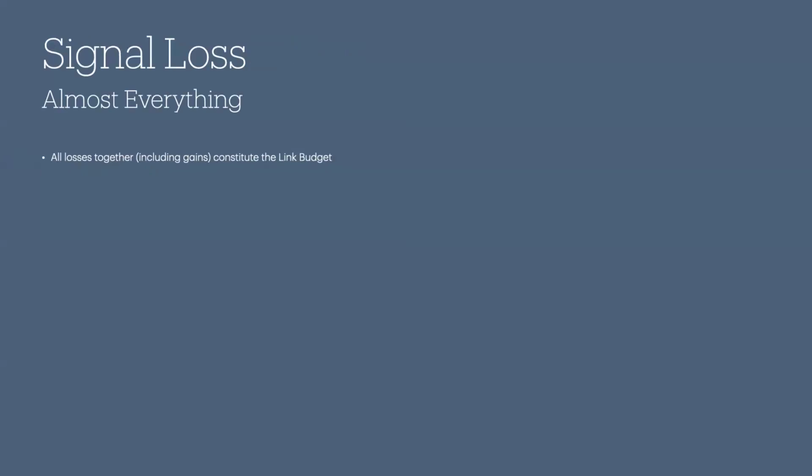Now, this is a little bit involved, but I'll just go through a link budget. A link budget is something we always do when we design a comms link with a satellite. We look at all of the places where we lose signal from the spacecraft to the ground. There's quite a few. And that's the equation. Sorry, it's a little bit involved, but it's just a bunch of terms added up. And we're dealing now in decibels, which is a relative logarithmic intensity. And I'll go through each one of those characteristics.